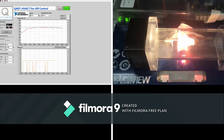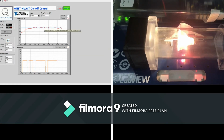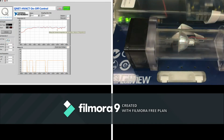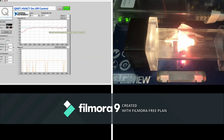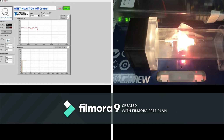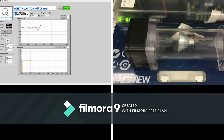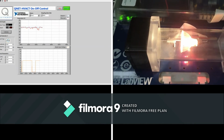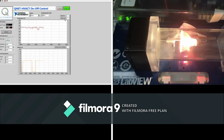If we cross this point, if we intersect with this point, then the heater will be off. Let's just wait. Okay, now the heater is off because we exceeded that value. Let's go back to 100. You will see that the temperature is going up and down, up and down. Sometimes above the line, the heater will be off. If we are below the line, the heater will be on, as you see. So this explains the set point temperature and also the measured temperature.